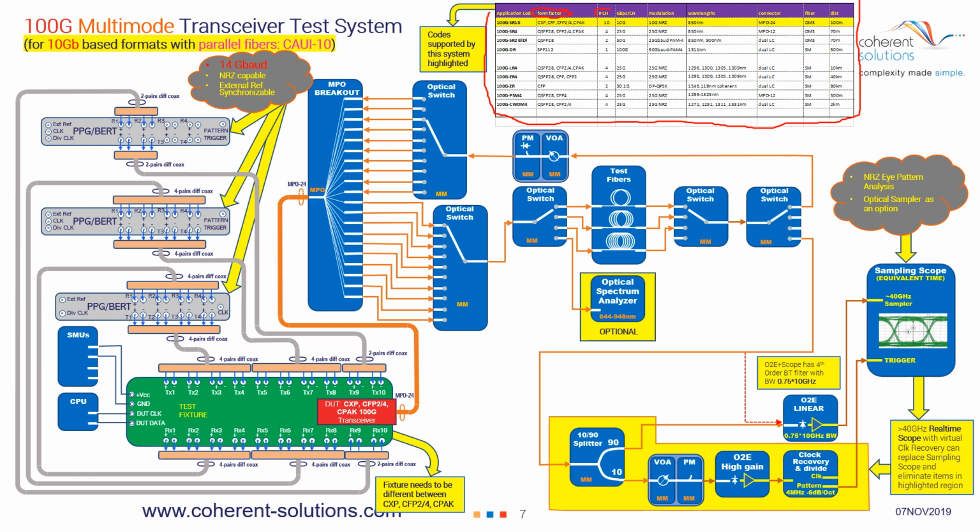In this next column, I give you a handy indication of how many independent data channels there really are for that particular transmitter. For instance, on this page, what is highlighted is the 100G SR10 transceiver. This particular transceiver has 10 independent data lanes, each one running at a data rate of 10 gigabits. That gives you a total of 10 times 10 gigabits or 100 gigabits. In addition, I indicate what kind of modulation format you can expect for this transceiver. In this case, this is a 10 gig NRZ, which stands for non-return to zero, essentially ones and zeros, as opposed to multi-level signaling.